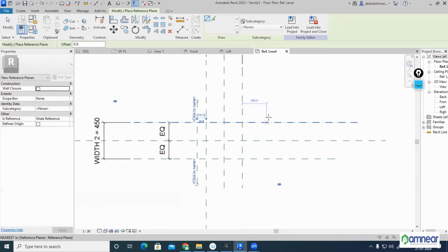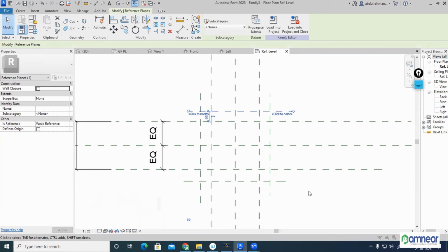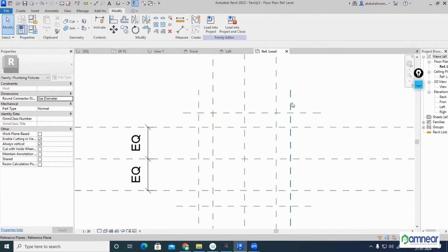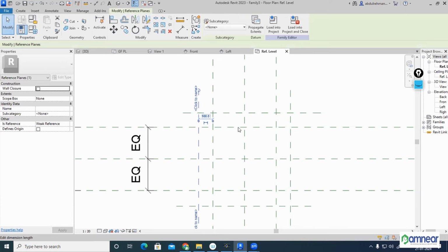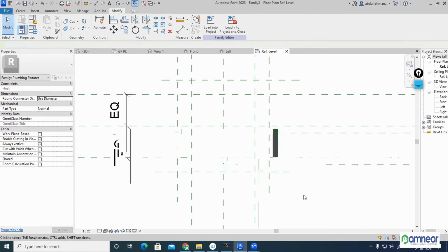And now the masonry outer wall. Let's say this one, this one, this one, this one. Now this distance I need 100 mm. This also I need 100. Okay. Fine. Here I need 100, and this was already 100 before. So this is 100, and this is 100, and this is 100. Here also we should. This is already 100 only. Here we should adjust that in loop, 100 mm. So outer wall is ready.